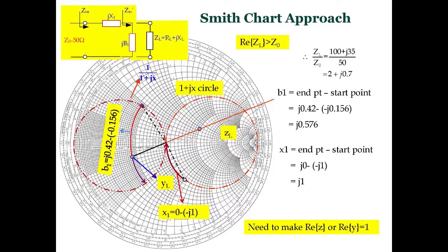So here I'm going to use the standard Smith chart, go over 180 degrees to this side of the chart, and this is the G equal 1 circle now. Now I'm in admittance coordinates, and I want to add shunt inductance or shunt capacitance to take me either up to this part of the circle or down to this part of the circle. Those are the two solutions, by the way, graphically now.